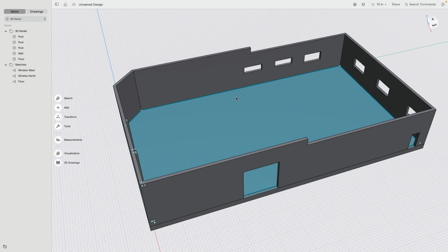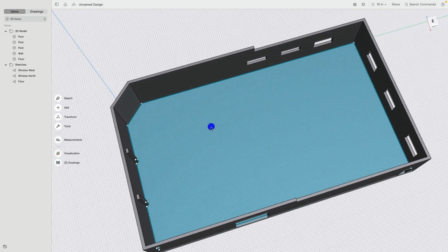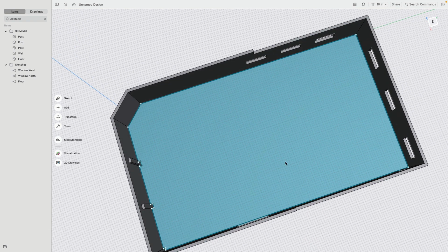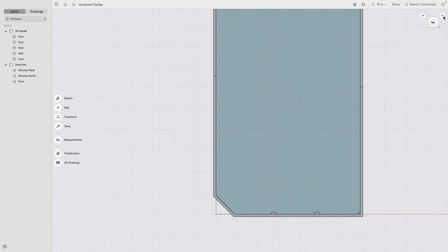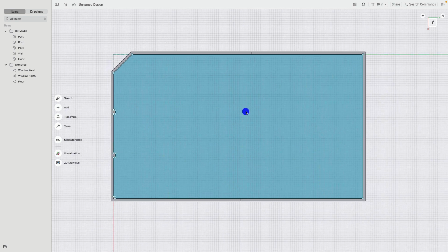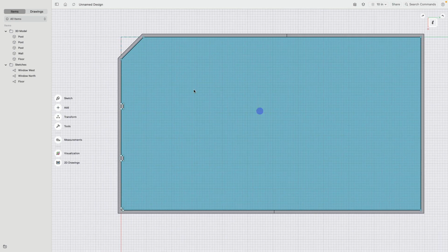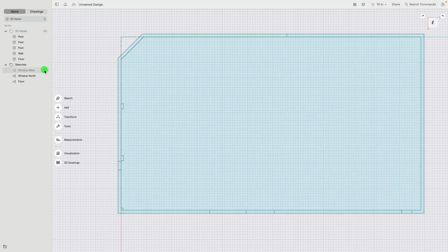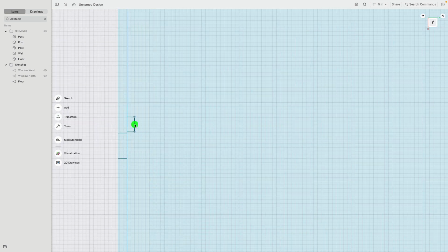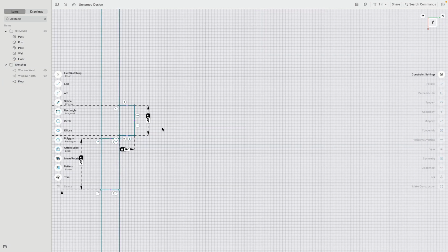We have now basically everything set up for the walls, and at this point now it's time to go ahead and actually plan out where are the positions of the I-beams and the support elements. So we can go into the top view. Maybe let's rotate the view so we can better zoom in. There we are. And the body I want to turn off. These north and west sketches I don't need anymore. I can zoom in, click on the sketch, then I go into sketch edit mode.